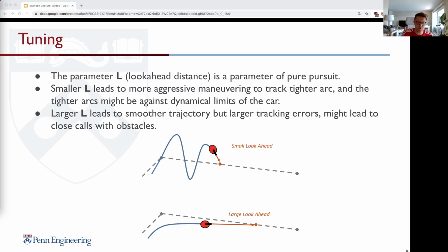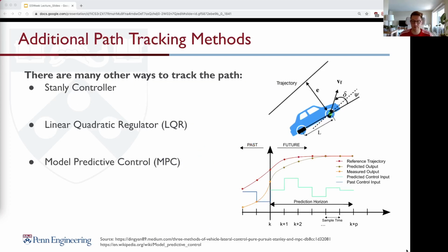For example, if you drive to a curve, or if you drive close to a wall, you miss that you need to drive a different curvature and calculate a different angle. So for you, that means you have to tune this parameter very, very carefully, and especially for the racetrack you're driving on. Here you have a wide variety of add-ons you can do, but this parameter is the most important one.